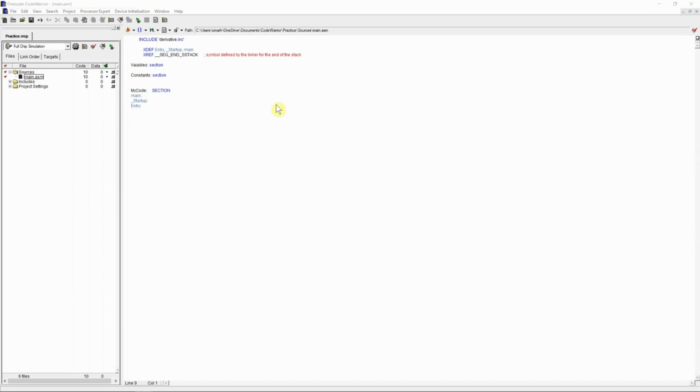The next addressing mode that we're going to learn is called indexed addressing mode. And for this one, we have to learn how to identify a constant in a different way. So far we learned how to identify a constant using the DC.B keyword. So this will identify the constant named con with the value 1.